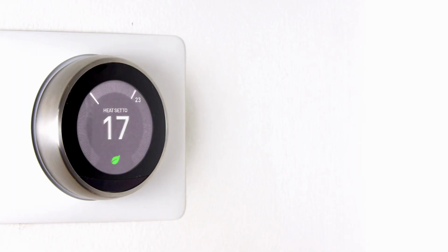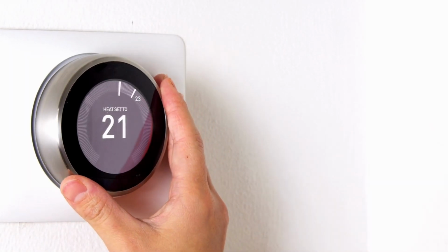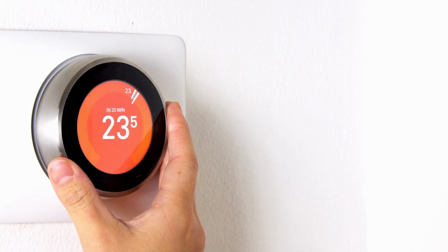AirReps offers the Daikin Variable Refrigerant Volume, or VRV systems, which consist of outdoor heat pumps and multiple indoor fan coils. With VRV, multiple zones in a building can be controlled to their own temperature set points. The VRV system requires a robust control system, which is provided as a package with the VRV system.